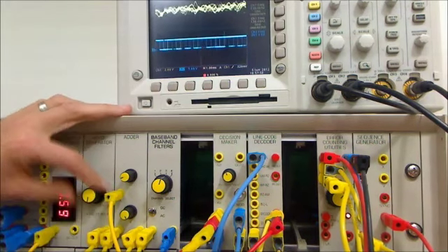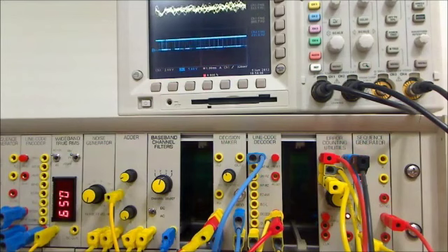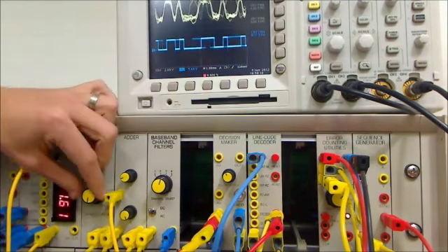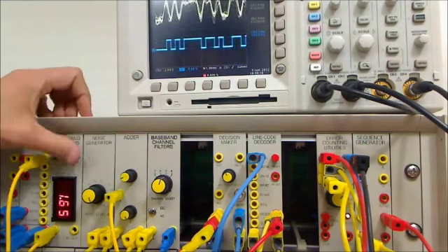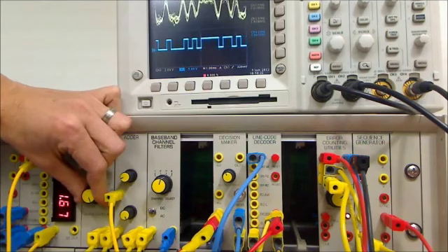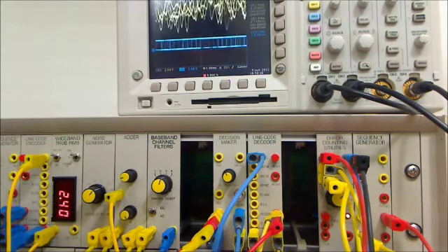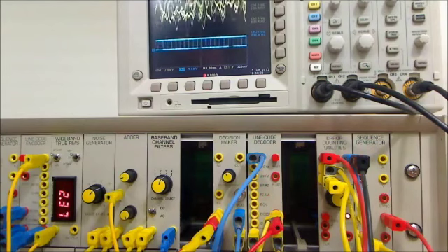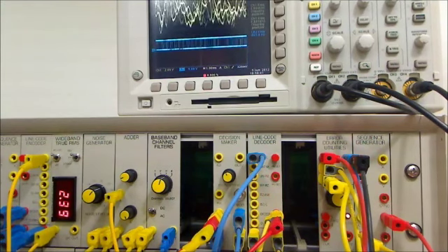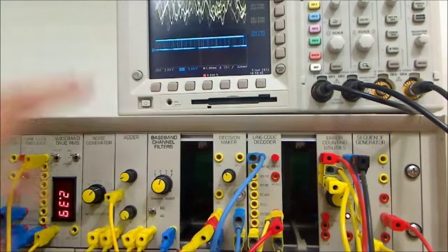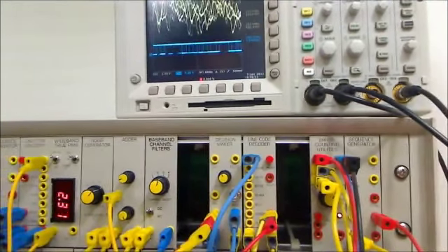So now, using the calibrated knob on the noise generator, we can easily move in calibrated 2 dB steps. So now we have a reference measurement of 6 dB. We can simply take the rest of the measurements off the true RMS meter step by step with the noise generator. Makes it very easy for students to take multiple measurements to define the bit error rate performance curve. So what we have briefly is a procedure for taking bit error rate measurements in a noisy channel at baseband, and if you want to work at bandpass, you can add modulation and demodulation for viewing other passband schemes and quadrature schemes.